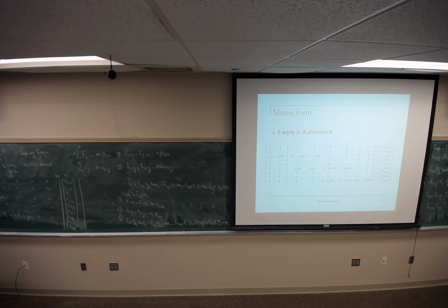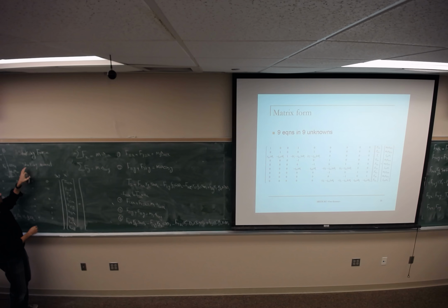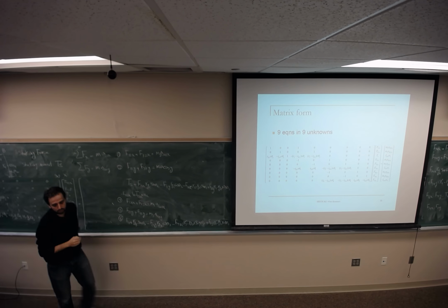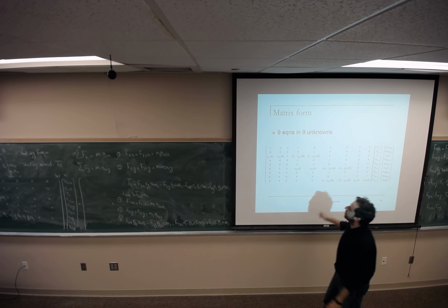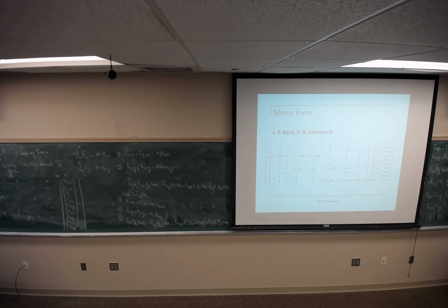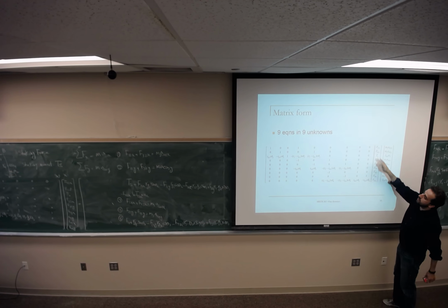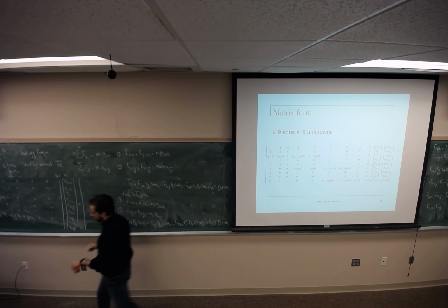How can you add them up? You add F21x plus F41x for the x component of shaking force, Fsx, and for the y, F21y plus F41y, Fsy. So shaking force in x direction, shaking force in y direction. Shaking moment would be the torque coming from the ground or the motor that we labeled as Ts. So after you find this value, you can find shaking force and shaking moment.